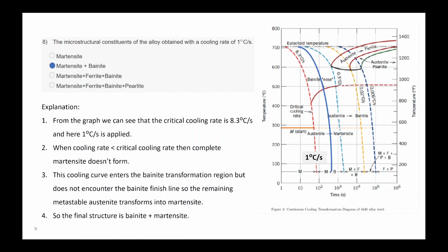Ma'am, can you explain that source and sink of dislocation? What do you mean by source and sink of dislocation? Source meaning how they'll be generated, and sink meaning they'll be going there and will be part of that particular thing. So for example, your grain boundaries are mainly called source and sink of dislocations. Your grain boundary areas don't have a crystalline structure, right? So dislocations can be generated from there, and they can go there and become part of a grain boundary. So they won't be counted as dislocations then.